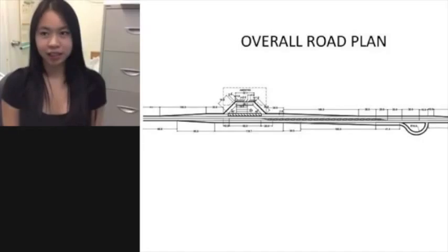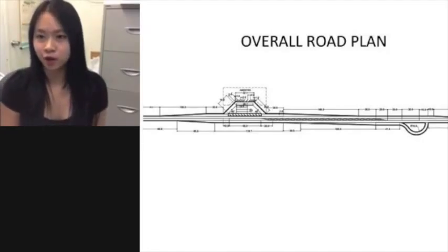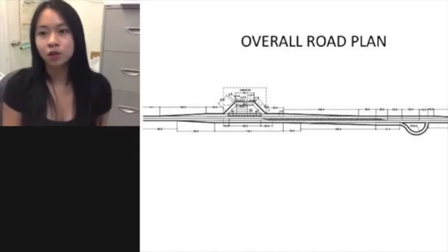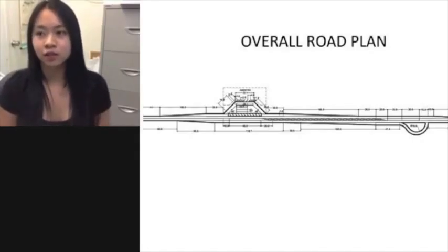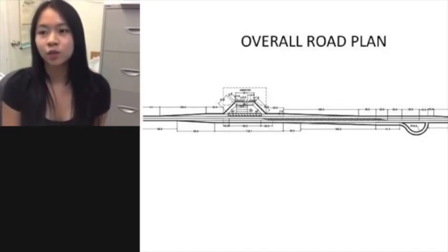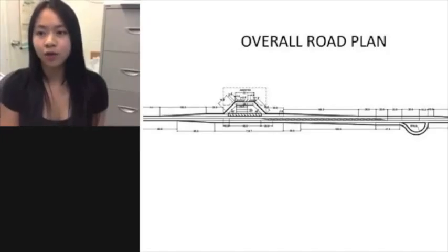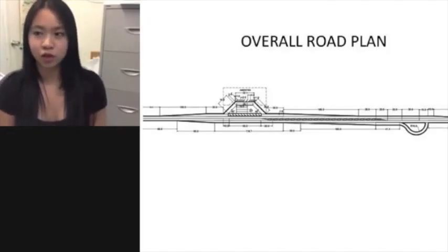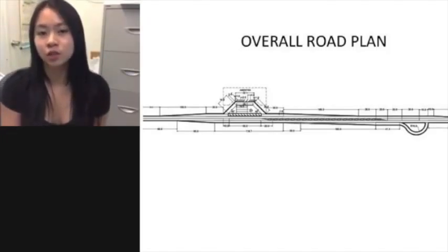The entrance lane is facilitated with a diverging lane for vehicles traveling along the road adjacent to the rest stop area, as well as a turning lane for vehicles traveling along the road on the opposite side, as they would head towards in the opposite direction. The exit lane is facilitated with a merging lane to safely merge onto the highway for motorists who intend to travel along the road adjacent to the rest stop area.